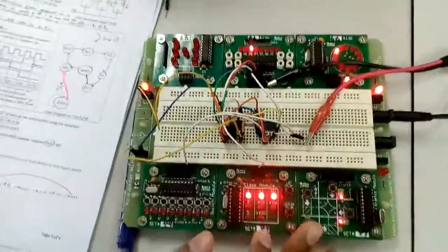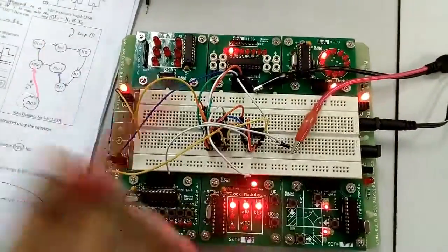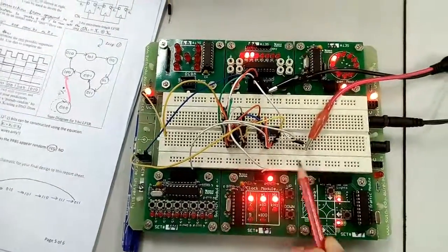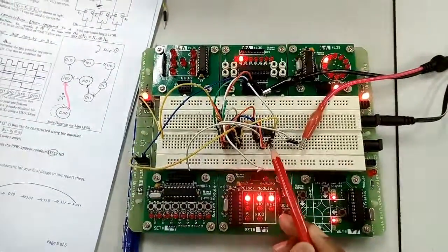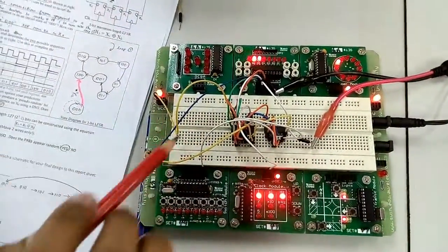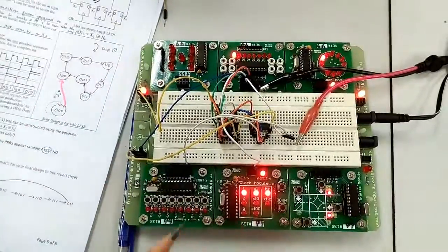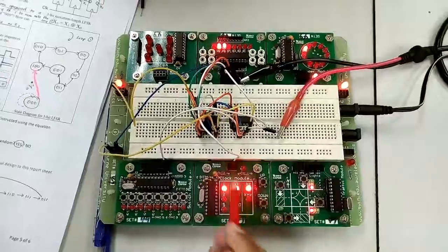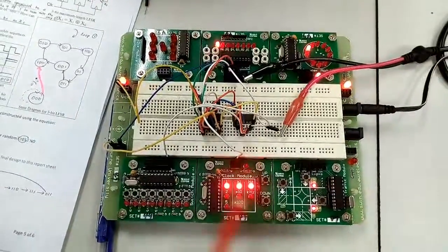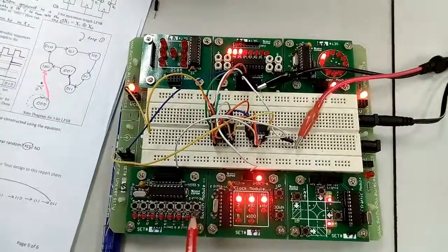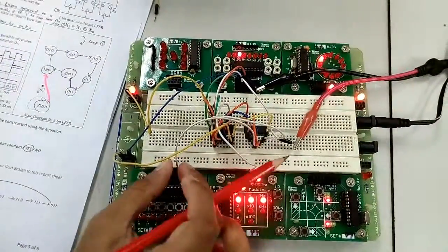And part 2. This is the construction of the linear feedback shift register. It is constructed from a shift register, the 164 IC, and an exclusive OR IC, the 86. This is arranged in such a way that the shift register goes through the maximum sequence of states. As of now we've set the frequency to 1 Hertz so you can see the states clearly, and you can see the switch is at 0, that is, it is at ground.